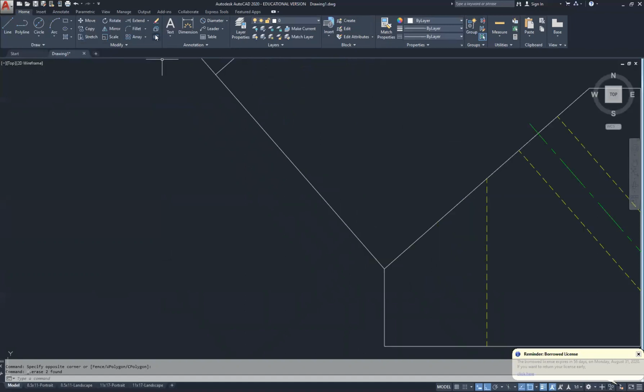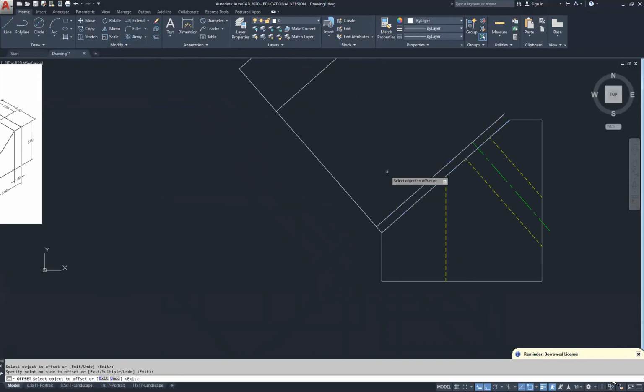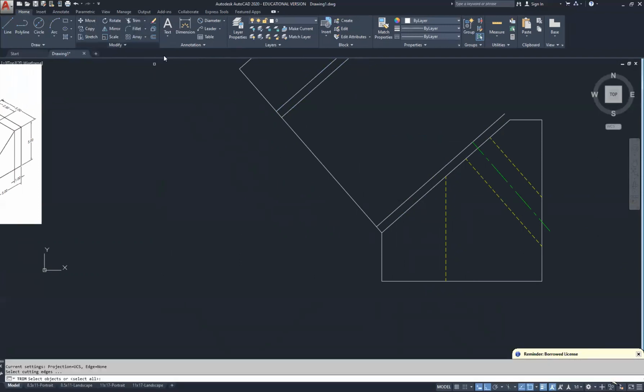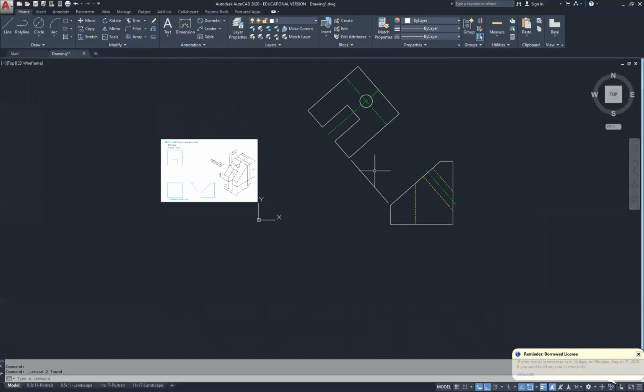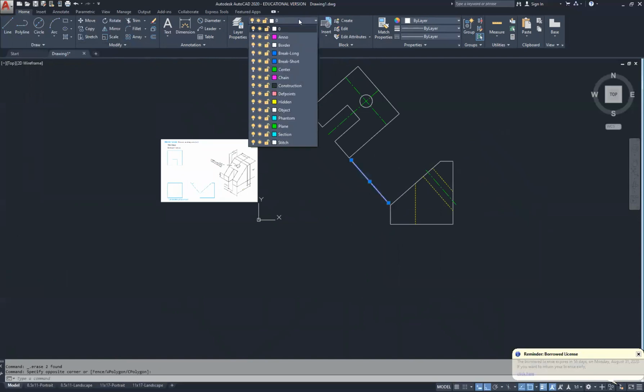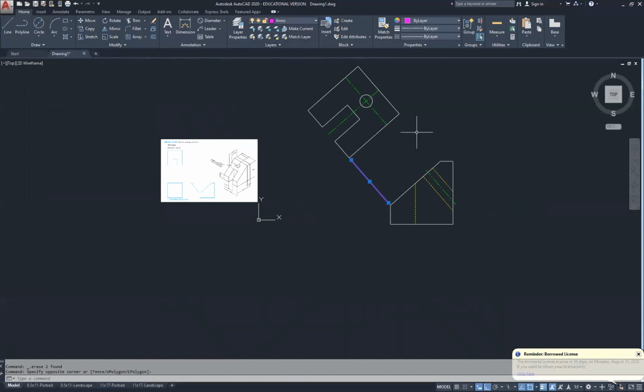And then I'm going to go ahead and use the offset command again. I'm going to leave it at 0.25 and hit enter, selecting that line and coming out this way, and selecting this line coming out that way. To break, we use the trim command on that projection line. I'm going to change this line type here to a reference line, showing the projection of our auxiliary view.